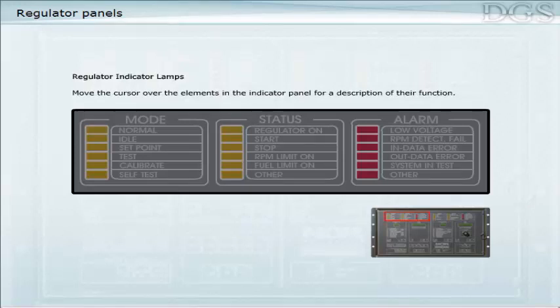Test mode is only selectable if the command handle is in stop. The system may be set up with all input data simulated instead of real sensors. The system may be set up with special calibration signals or routines. Calibrate will also be lit up if the Cal button is activated. Self-testing of computer memory is activated by pushing lamp test. This will respond with reg up if memory is OK, or with error if there are any memory problems.